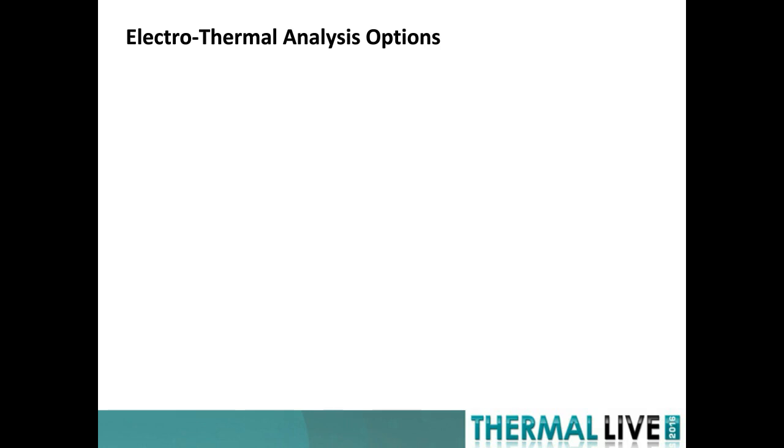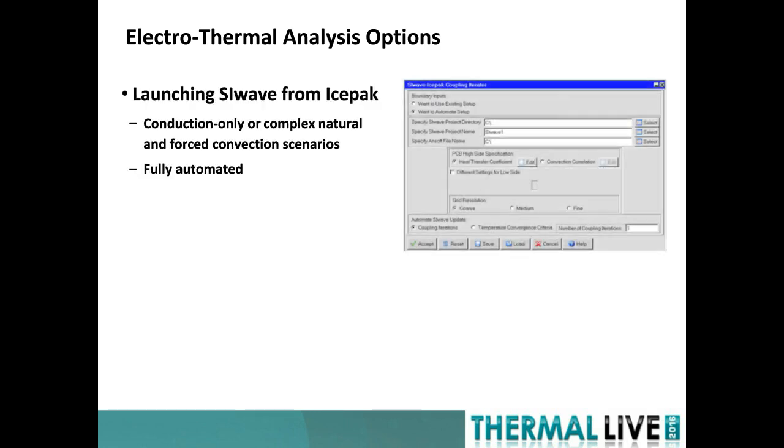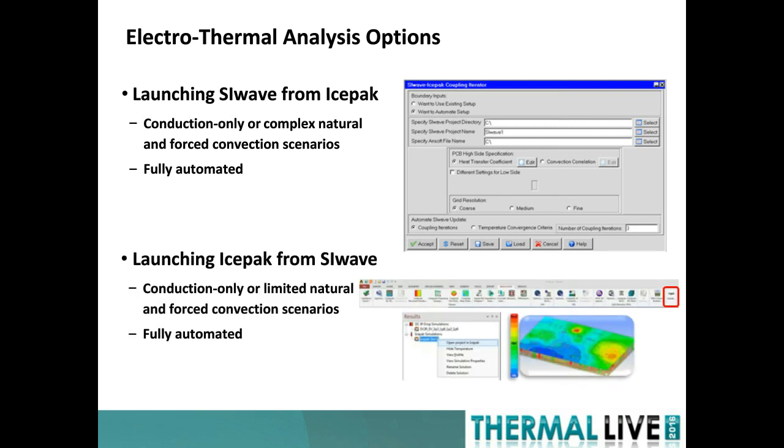Now, before I move on to the mechanical side of things, I just want to mention here that there's a couple options for launching this electrothermal analysis. You can launch it from IcePack, and you can also launch it from SIwave. Both ways are fully automated, so the coupling proceeds automatically until convergence. Also, both ways allow you to perform either a conduction-only or a full CFD simulation.